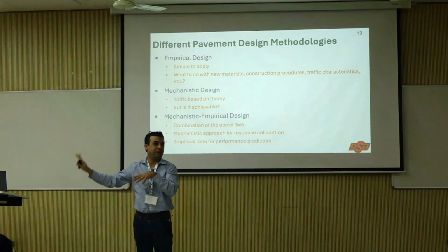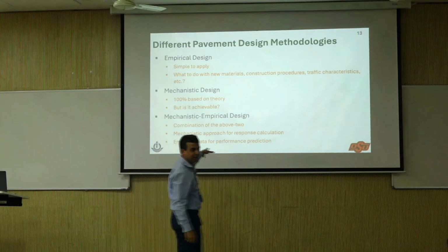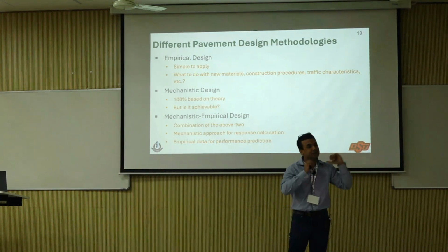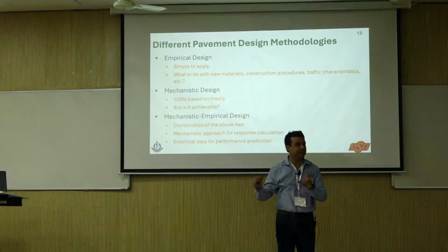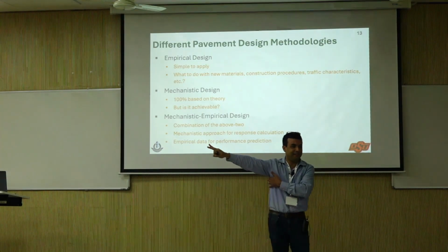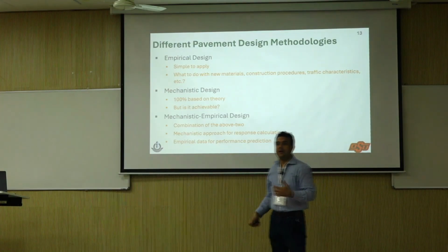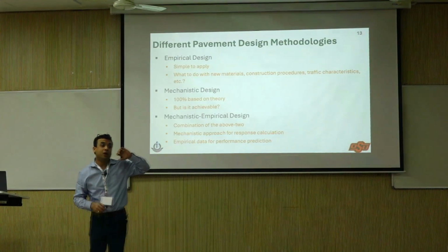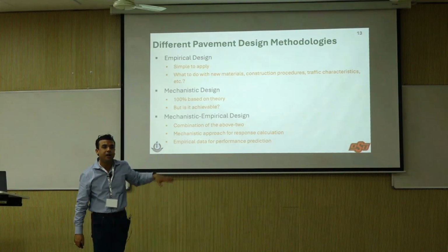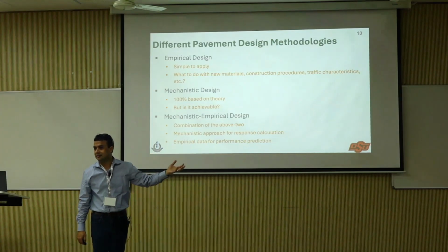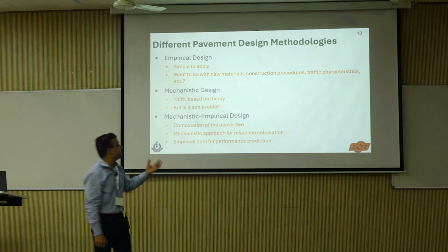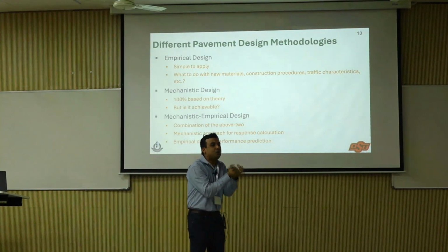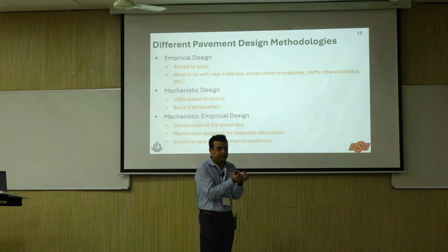The best we can do is ME, right? We have to go as far as we can with our mathematics, and then magic happens, and then cracking. That's basically what it is. If you go into MEPDG, the pavement mechanistic empirical design, there is something called global calibration and something called local calibration. That's what this is. Why are all these states suffering to do this? Because not everybody has been able to do successful local calibration.